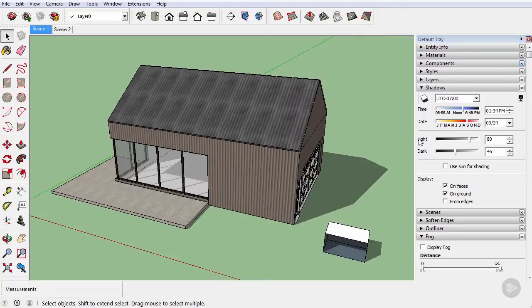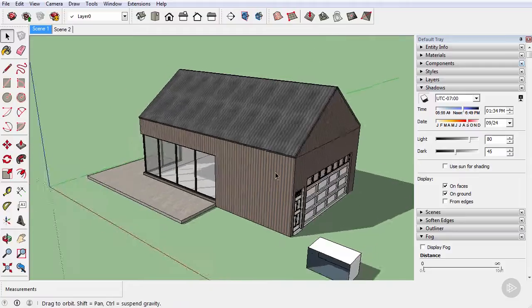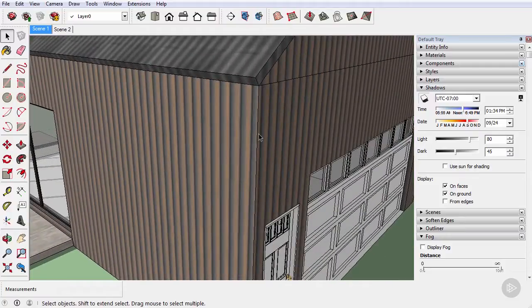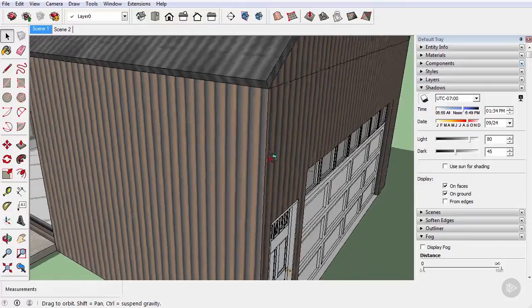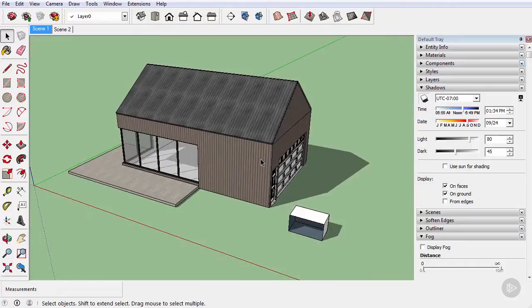One thing to note here is that even though the lighting system inside of SketchUp is pretty simple, so it's basically a binary system, a given surface is either in light or in shadow, enabling shadows does affect performance. So that's why in my working style I work without shadows, but of course if you need to use them in your perspectives for presentation drawings, then it should be enabled. But yeah, it does affect performance, so we'll keep this off for most of the modeling process.